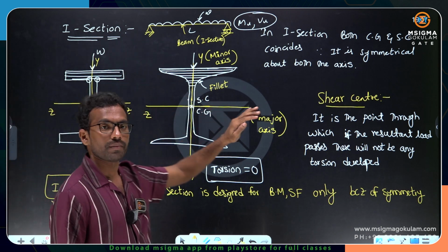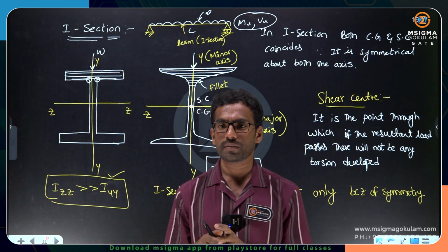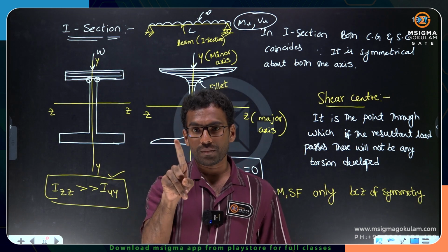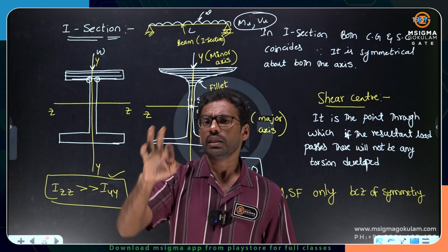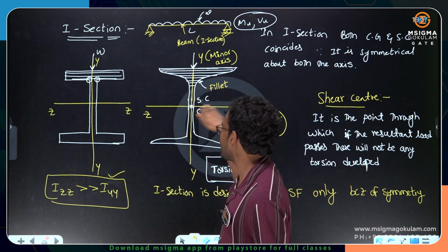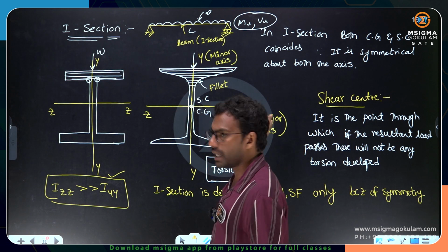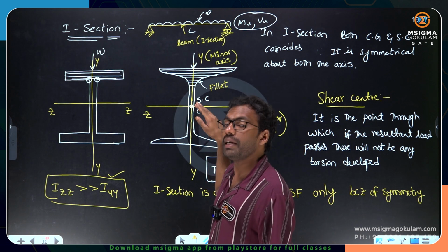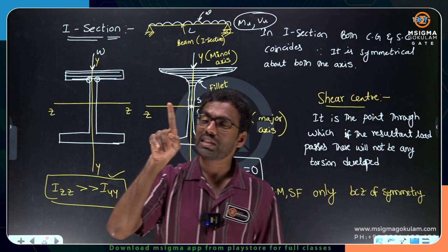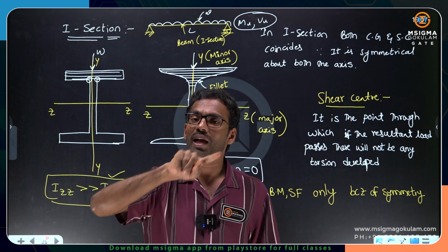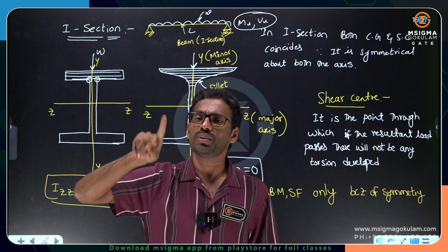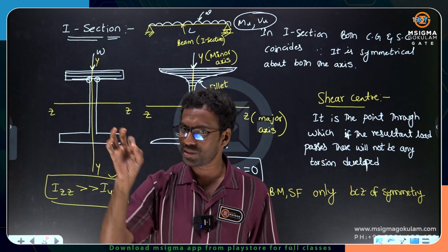So, my dear friends, the very important conclusion is that the I section is the section which has the largest moment of inertia about its horizontal axis, which is in fact the neutral axis. About that, bending is occurring. So a section which has the highest moment of inertia about the neutral axis is the most efficient section to resist bending. Is it clear to everyone?